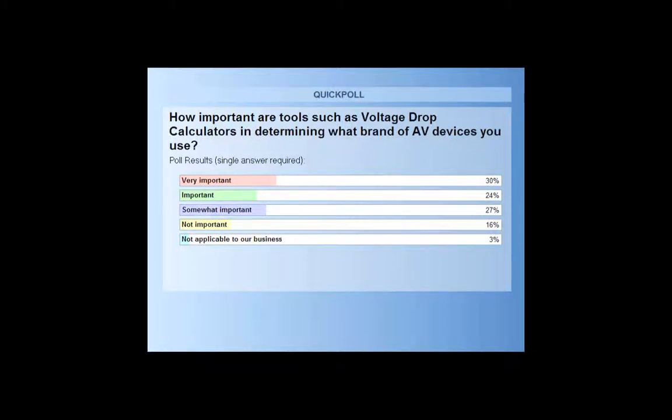And then the same thing with all of those other selections, like the temporal or non-temporal. So whether you're driving a continuous tone or using the three beeps, the beep, beep, beep, when you're using your horn, that also affects the current draw. That's why we specify in the calculator which you're using, because when it does the calculations, it takes those into account for the current draw that the device is using.